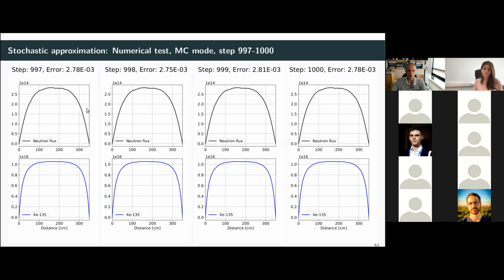It converges. And because you are combining all the solutions from the Monte Carlo solver over all the iteration steps, you are also combining the random noise together. Now, when you combine random noise, it is eliminated from the solution to some measure, because random noise deviates the solution in a positive or negative direction, right? So if you have many positive and negative deviations from the mean value, they combine to 0. So by combining all the solutions together, you are not only stabilizing the iteration, but you are also reducing the random noise in the solution.